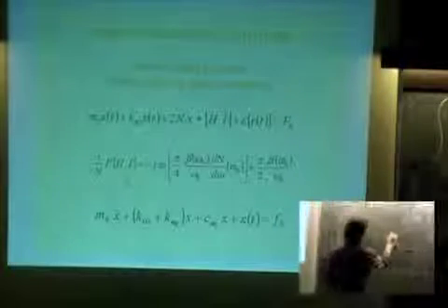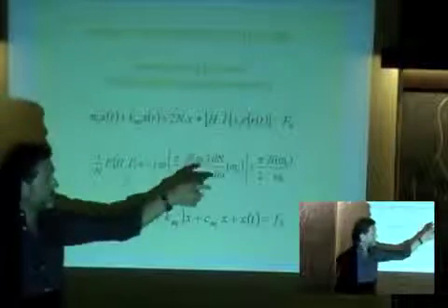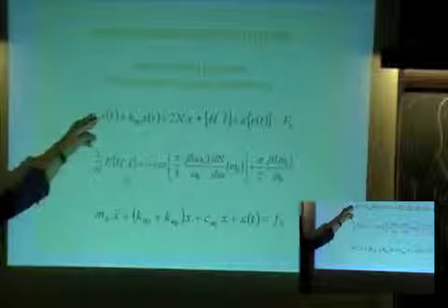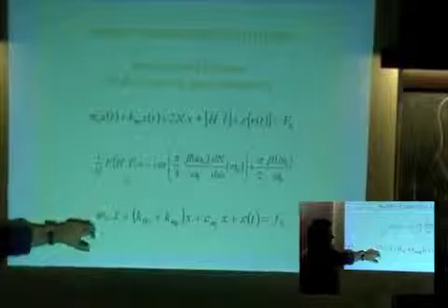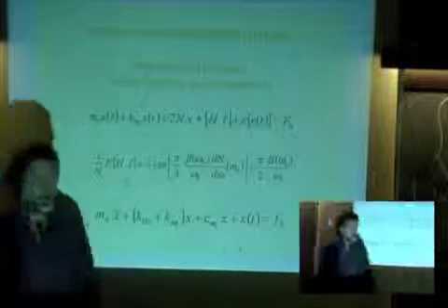So suppose that all the set of frequencies are located in a relatively narrow band, and then you have some reference frequency omega 0. Then from this result you can use an approximation for this inverse transform, and starting from this approximation you can get the final equation in the time domain, where you have an actual dissipation term, then the reactive term that is just an elastic force, plus the presence of this epsilon element. So actually we have to discuss the remainder term.